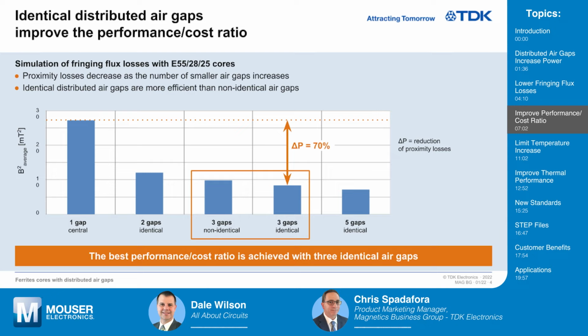Okay, so let's talk about performance and actual performance here. You're looking at actual thermal image tests right here, and we're going to compare two frequency levels, and this is important as we get further into the discussion. So, we measure the performance of a transformer choke at different frequencies, and if we look at this first gap at 50 kilohertz and one gap at 200 kilohertz, we can actually see the thermal imaging of this particular build.